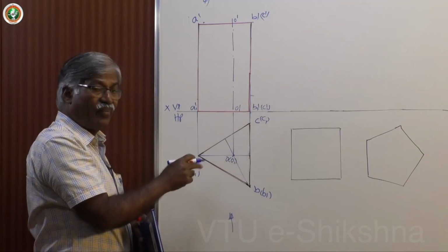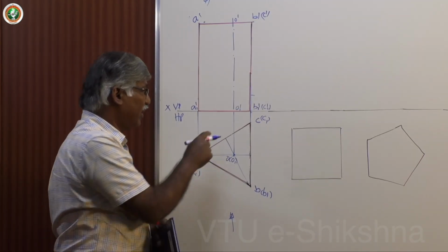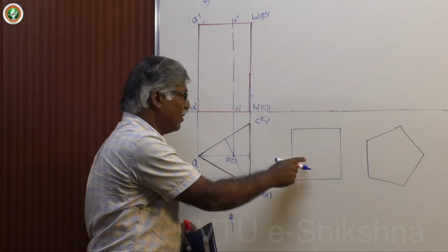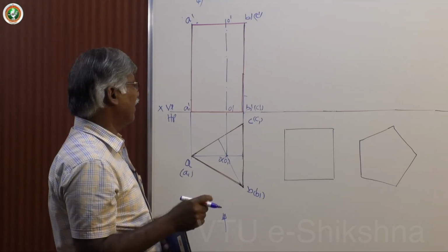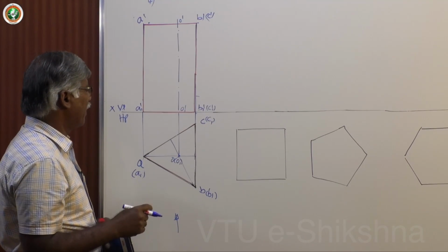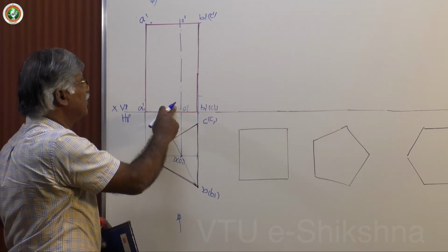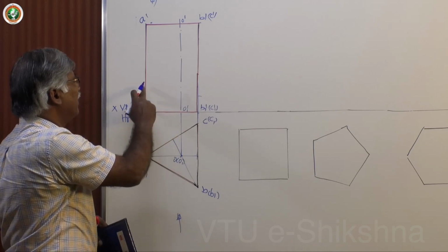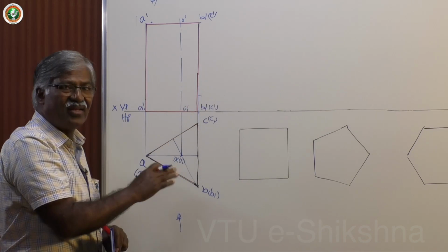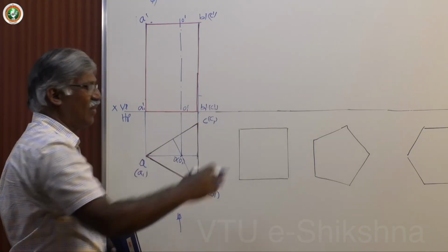This must be drawn by obtaining the center of the lamina, not the mid portion of this. Please have that in mind. That is true in case of hexagon and square, not in case of pentagon and the triangle. Now it is biased towards the right in this case. This is the O1 center, axis reference, and these are required thick lines. Here no hidden lines are shown because CC1 is coinciding with B1. In future you will get that.